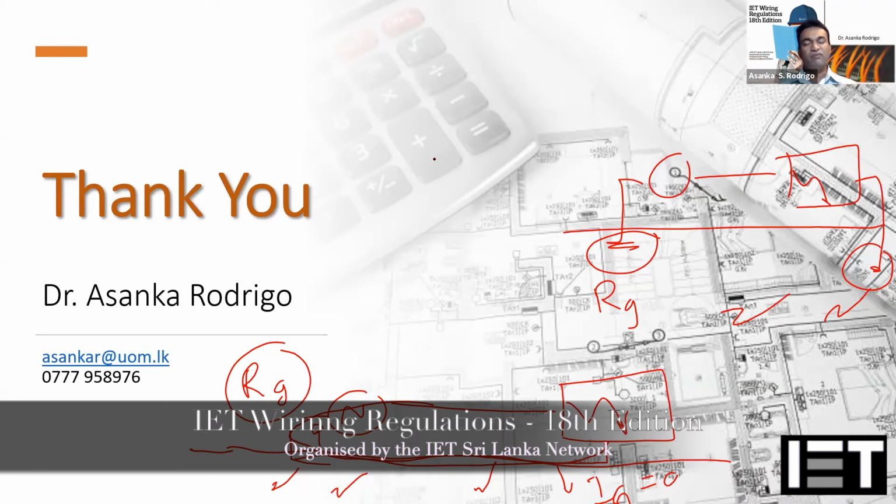But when you have an underground cable, normally an armored cable, there can be a situation where there is insulation failure. Due to the live wire insulation failure, there can be earth leakages. In the utility system, you don't have any device to detect that type of insulation failure, especially with the armored cable. Earth fault will not be detected by the utility because the utility doesn't continue the earth wire. So it's a low impedance, high impedance earth fault.